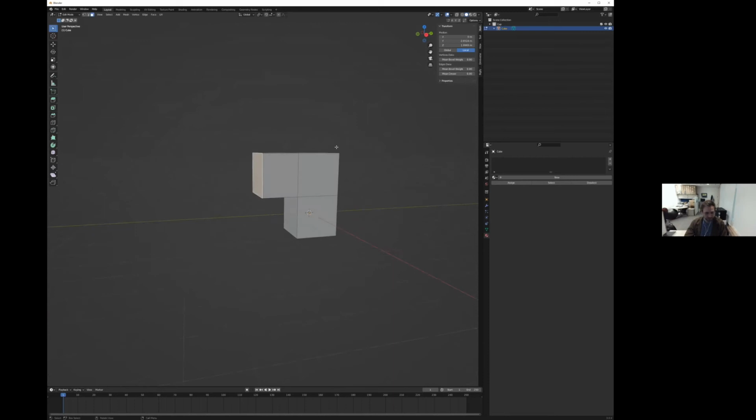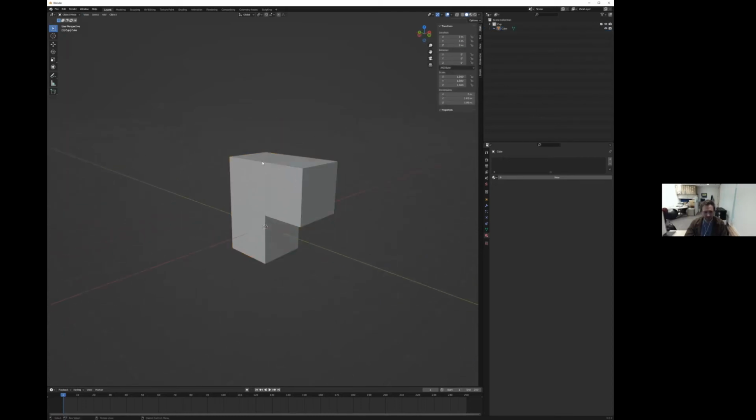That's not equal. Something that I did miss. If you are working with a keypad, you might be able to do this on a laptop as well. Right now we're looking at the object in a perspective mode. We also have the option of looking at it in an orthographic mode. Orthographic really takes away a lot of the depth. It essentially looks at your object on one plane, if you will. And to show you that, I'm just going to press 5 on my keypad, and now I'm in orthographic.